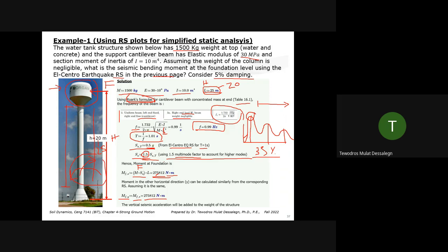This is just to show you how the response spectrum plots can help you get the reaction forces at the base. Once you have the moments, you have your vertical force. You can also use the vertical acceleration to get the vertical force. These biaxial moments and vertical force from seismic acceleration are dynamic. You will also add the static load, especially together with the vertical. So you have a vertical force and biaxial moments acting, and also shear.